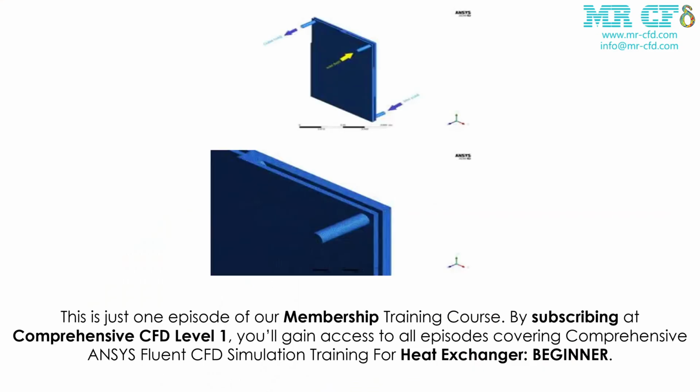The geometry of the heat exchanger is designed in Design Modeler software, and grid generation is done in ANSYS Meshing software. Inlet and outlet boundary conditions of both hot and cold flow are shown below. The mesh type is unstructured, and the total number of elements is 2,273,000.